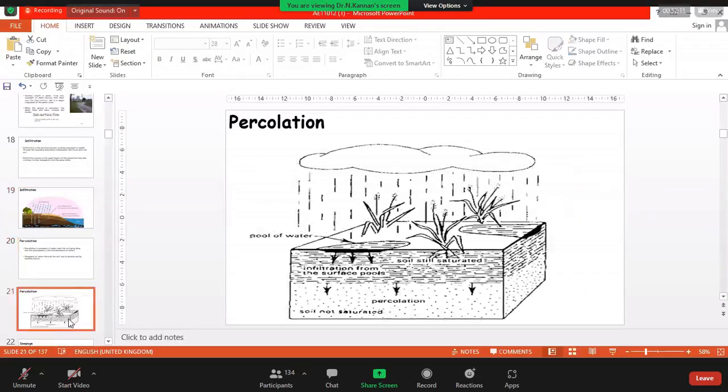With that note, I will move to this one. I have told you that from this parent material we are developing the soil. This scientific process is called soil genesis. Then we have precipitation, which is important for plants to grow. Then there is this layer where you sometimes have unfilled pore spaces, so you will have the infiltration. If the water is able to move further downward, that is percolation. If it is moving further, that is deep percolation, right?